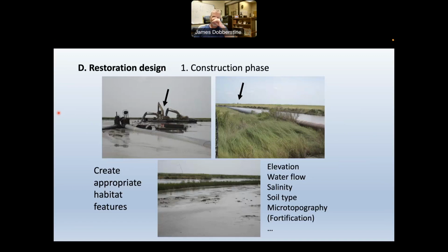All right. So in some instances, if you have an area that part of that marsh is going to be exposed to a significant wave fetch when we have these northers come in, which is often the case on the bay side of Galveston Island, then you have to incorporate in those instances some sort of protective, sometimes sacrificial erosion protection, right? To give the marsh that you're constructing time to establish in order to protect itself, right? So these are the kind of things that we have to consider as part of that.